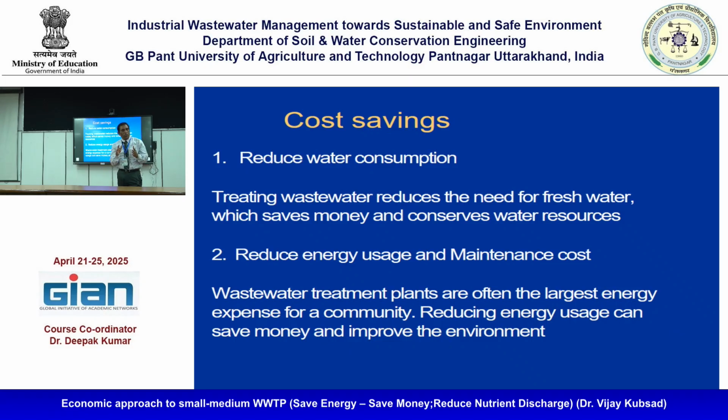If it is an industrial wastewater with high BOD, what will you do? You cannot apply aeration, it cannot be treated aerobically. What we do is anaerobic treatment, then the supernatant is collected, and then we give an aerobic treatment. So that is how we do a combination.